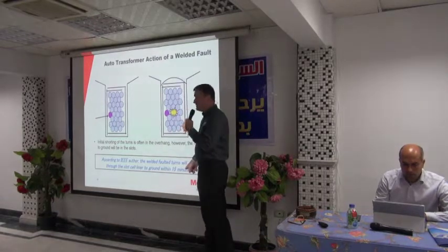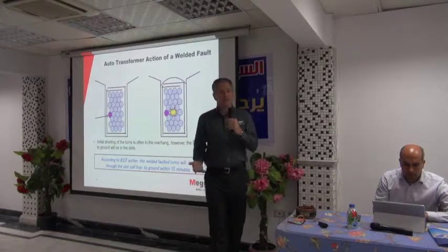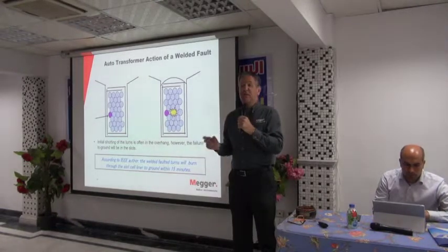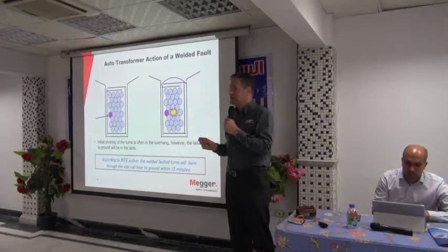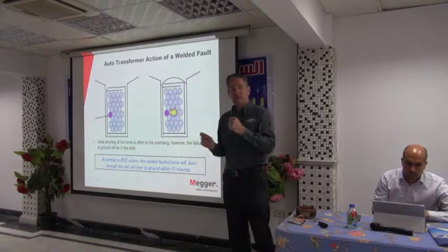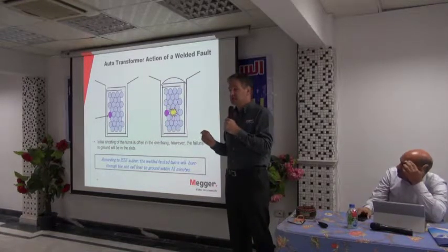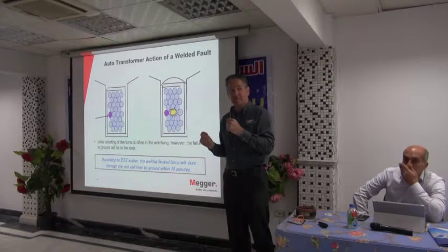This guy says 15 minutes. It doesn't matter whether it's 45 seconds or 15 minutes or 1 day or 2 days. It means you have very, very short time left before the motor fails. So we need to find the problem before you have a short circuit. And the only way to do that is to use a surge test. Otherwise you can't find weak insulation.